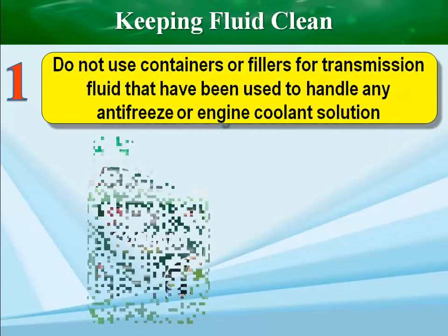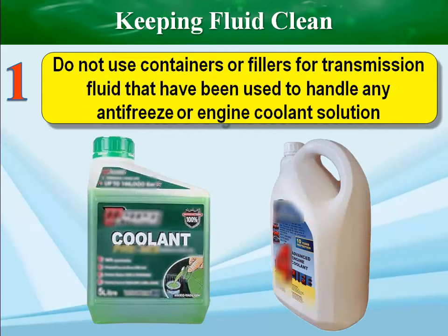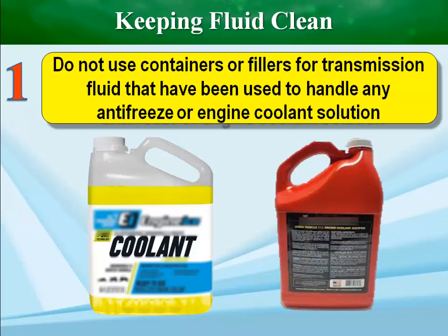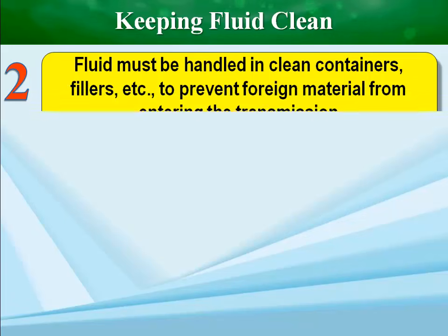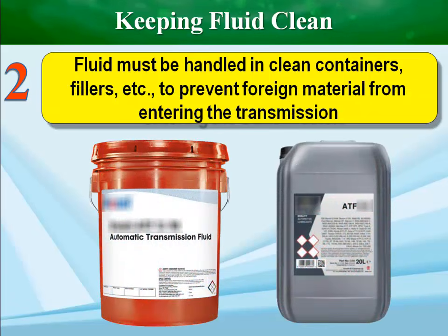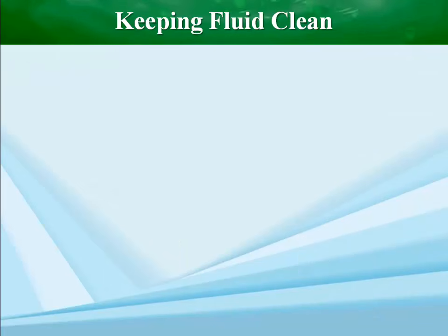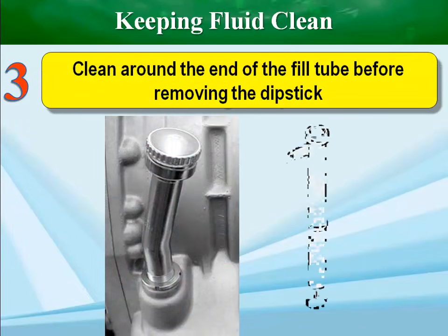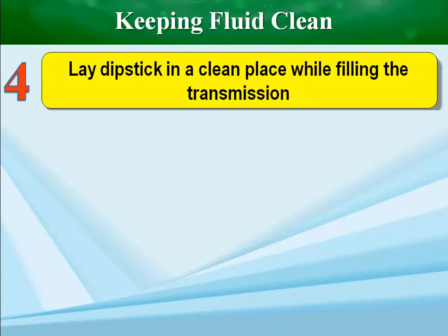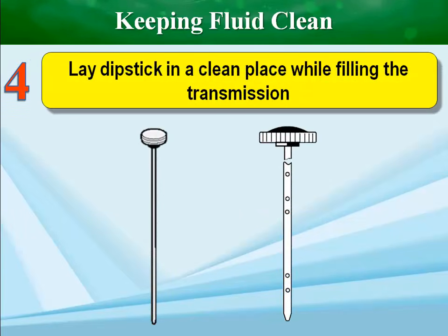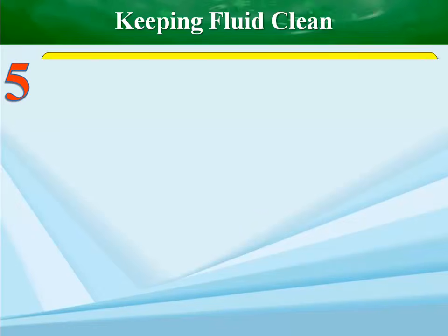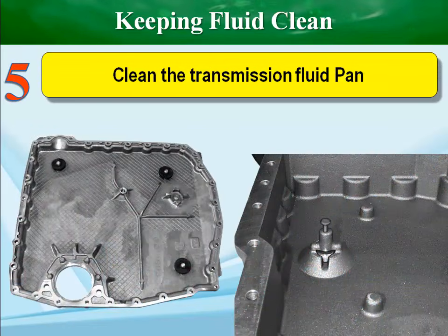Do not use containers or fillers for transmission fluid that have been used to handle any antifreeze or engine coolant solution. Fluid must be handled in clean containers, fillers, etc., to prevent foreign material from entering the transmission. Clean around the end of the fill tube before removing the dipstick. Lay the dipstick in a clean place while filling the transmission. Clean the transmission fluid pan.